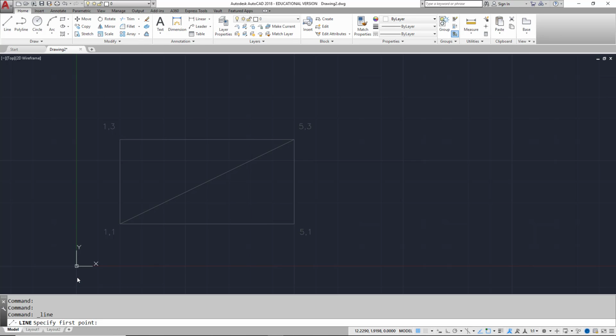The difference with relative coordinates is that the origin is not stationary at the intersection of those 2 points, but moves to the previous point. So if I was going to draw this figure on the screen, I would temporarily move the origin to the previous point. We do that with the @ symbol. I will now demonstrate how to draw this using relative coordinates.